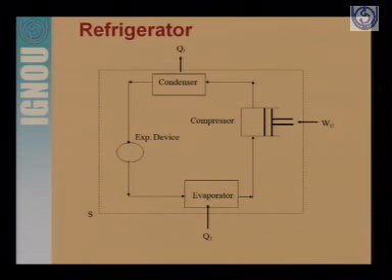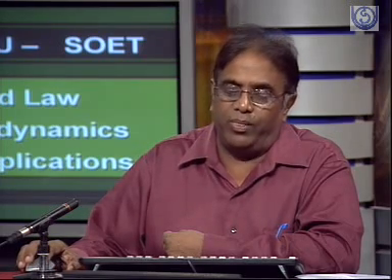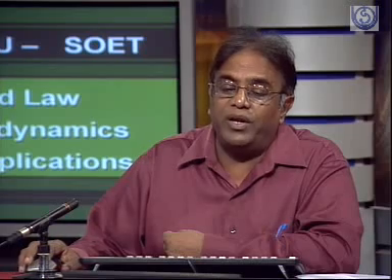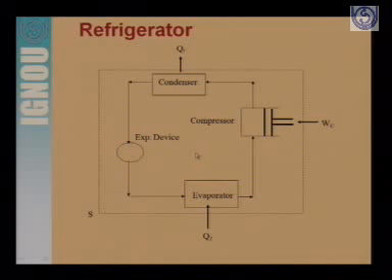There are different types of refrigerant like R11, R12, which are chlorofluorocarbons, and different commercially named refrigerants are available like R11, R12, R22, and like that. So the low pressure, low temperature refrigerant enters the evaporator, and here it takes heat from the confined space. Virtually, we can say that in the confined space we are keeping vegetables to be cooled in a domestic refrigerator. So here Q2 is the heat taken out from the confined space.